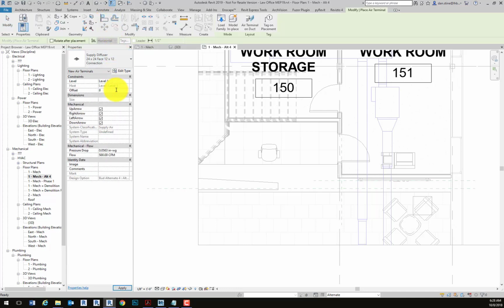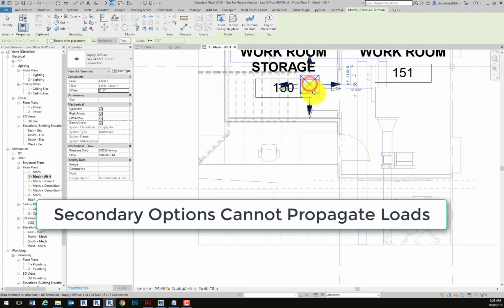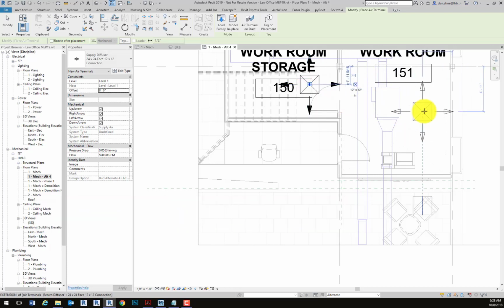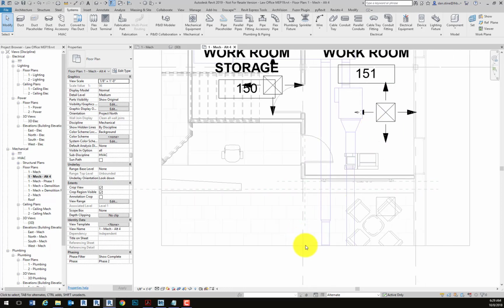information to this view, I just switched into that secondary design option mode called alternate, and now anything I model while that design option edit mode is active, and that's in any view in this project, not just this view. That setting down on the status bar that I just selected, alternate, is for the entire project. I'm in edit mode for that design option now. And so as I add things, they'll be part of this secondary design option.